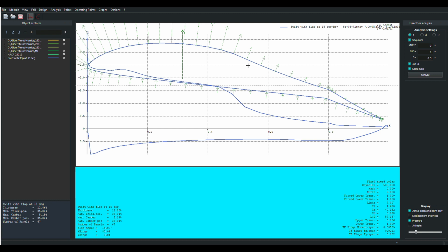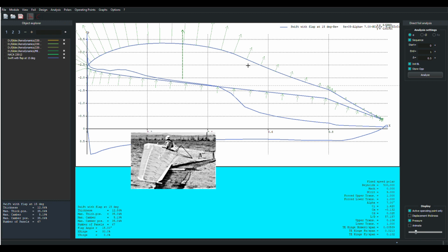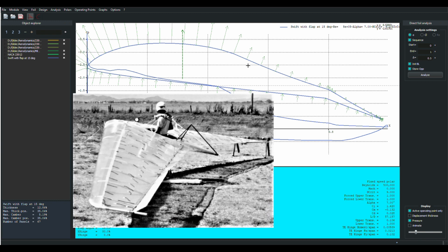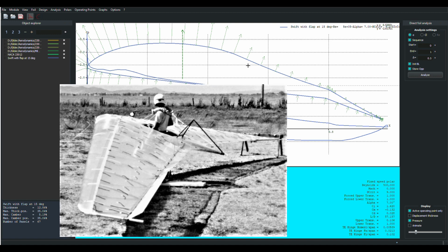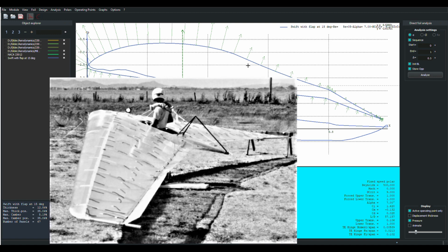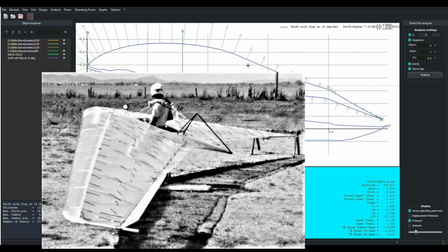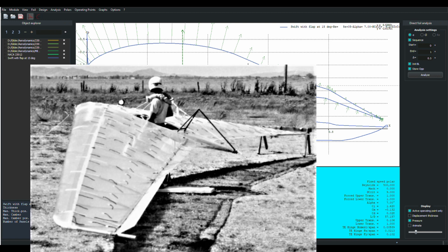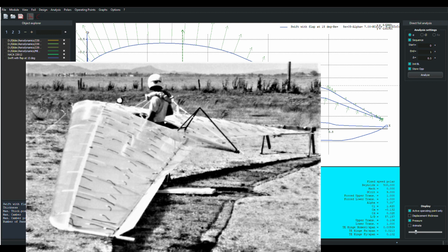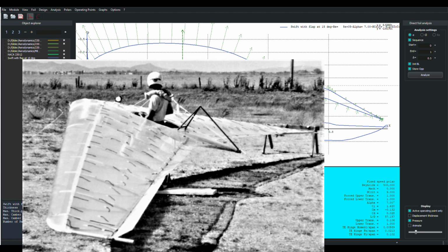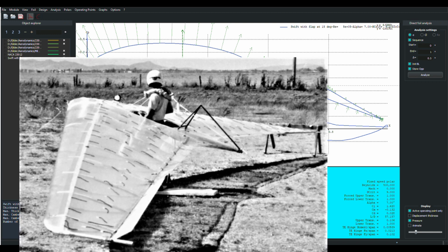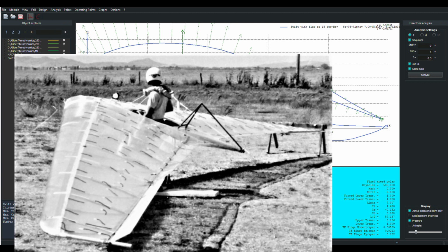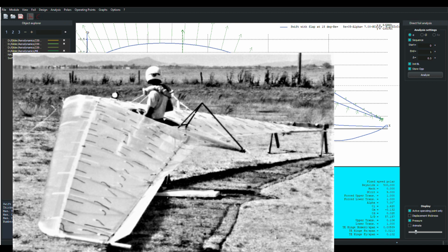And the other thing that I did on my original wing, I'll put back up a picture of my wing here. If you look closely, very closely, study the picture, you'll see that the elevon does not have any twist in it. It's in a portion of the wing that is highly twisted. There's about 3 degrees, 3.5 degrees of twist that occur in the wing from the root end of the elevon to the tip end of the elevon. The wing itself is twisted 3.5 degrees. But the elevon is flat.